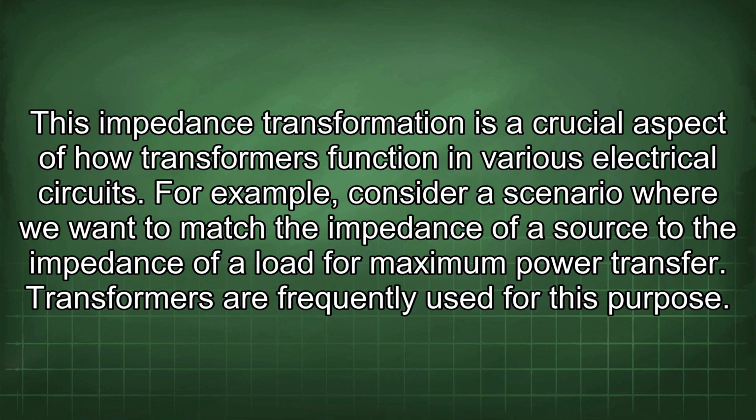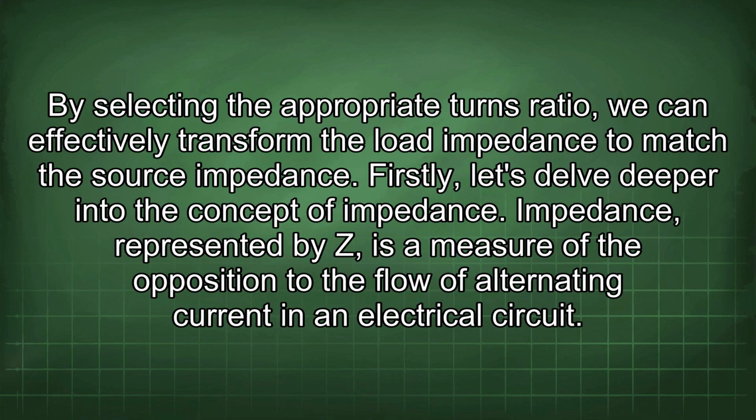For example, consider a scenario where we want to match the impedance of a source to the impedance of a load for maximum power transfer. Transformers are frequently used for this purpose. By selecting the appropriate turns ratio, we can effectively transform the load impedance to match the source impedance. Firstly, let's delve deeper into the concept of impedance.